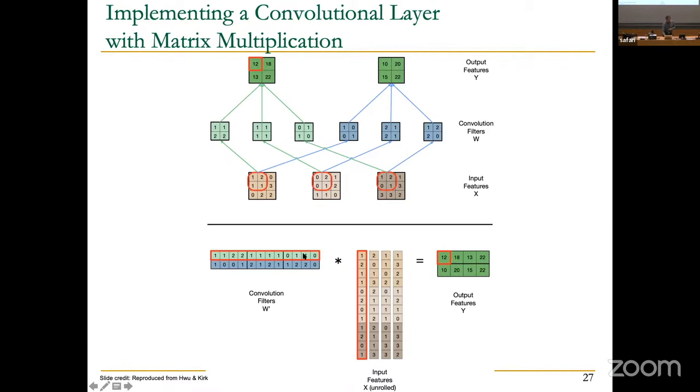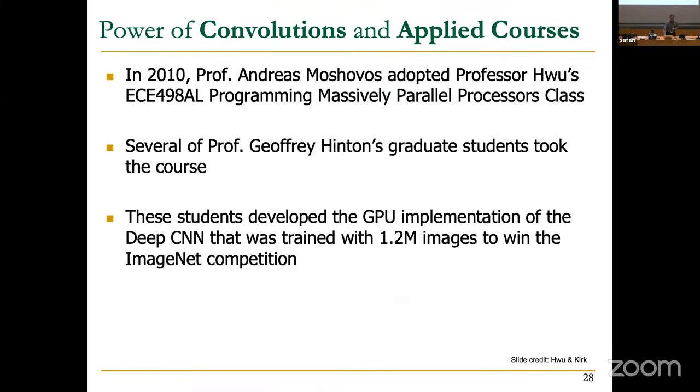And what we're doing is multiplying this vector with the input features. Okay, so basically this is matrix vector multiplication. Convolution can be implemented as matrix vector multiplication. It could be implemented using systolic arrays as well, as we will see. That's why people are doing this on GPUs as well as systolic arrays today. GPUs, hold on, we'll see.